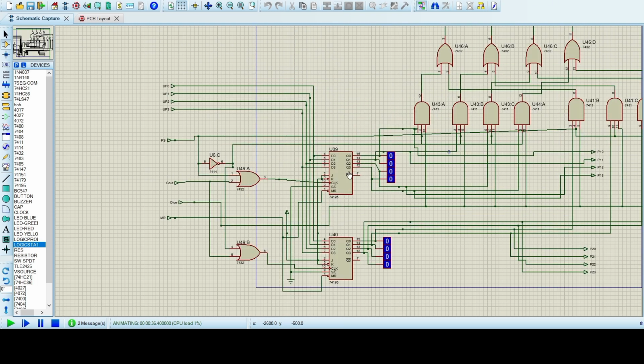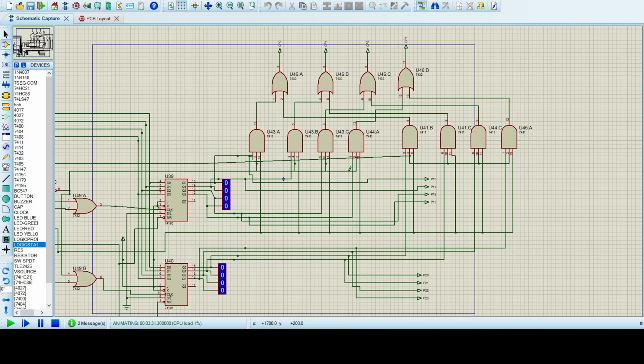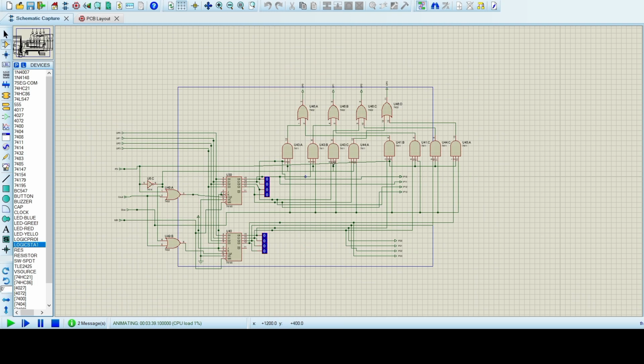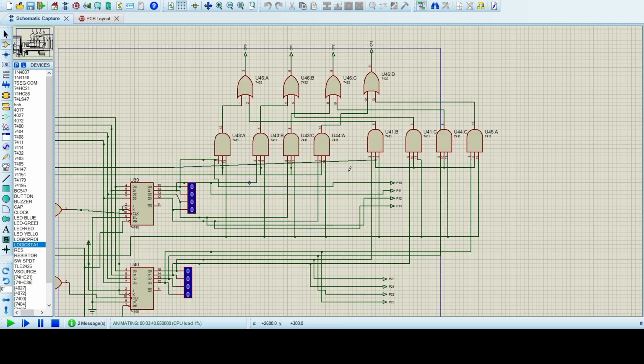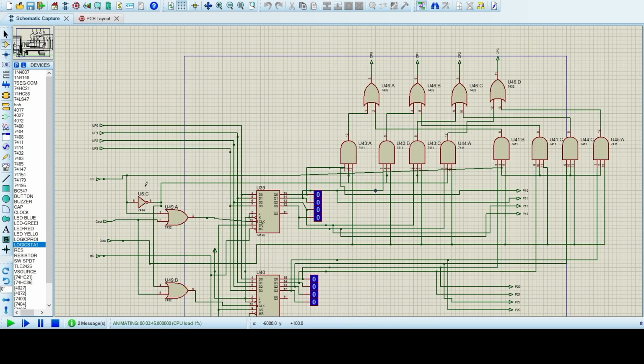And how do we calculate? Before checking out how the appropriate register is updated, let's check out how player positions are sent to the SL logic to calculate the updated position. We can see there are 4 AND gates for each register. So we have two registers, and there are two additional inputs for each AND gate, which will be one the player selector and the other the dice press signal.